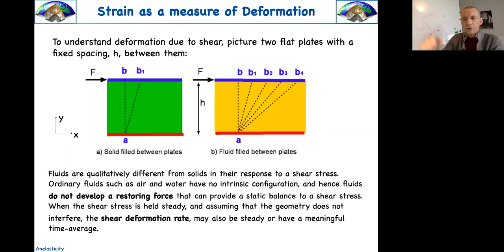But if you take a fluid, if you imagine now two plates, typical viscous, Newtonian viscous behavior, you apply a shear stress and you are going to get a reaction. Well, for an ideal fluid, there is no reaction because mu is 0 and the fluid is standing, but that's the ideal fluid. Feynman was calling this dry water, just to express this paradox. But for a more realistic, viscous fluid, when we apply a shear, part of the fluid will flow.